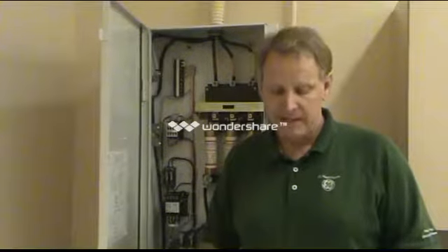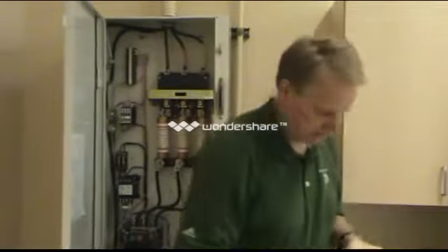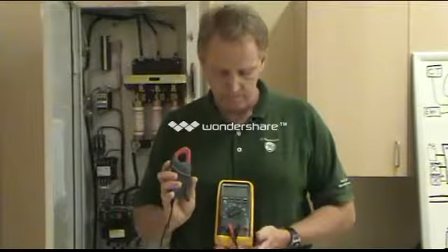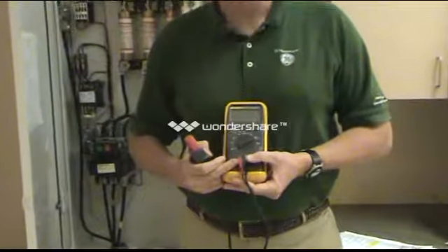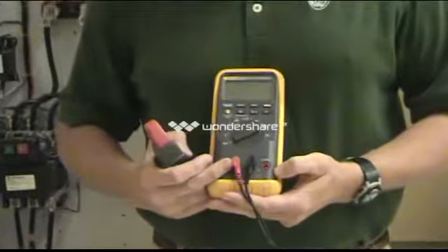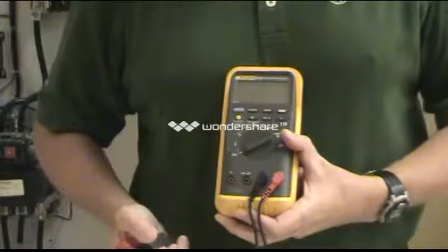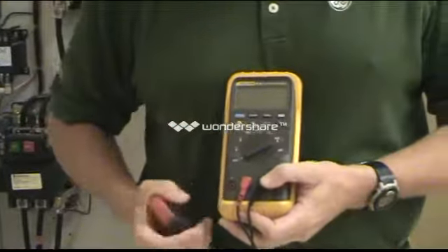Panel currents. This is a section that most people are uncomfortable with. Typically in GE, we haven't been measuring currents, so we're going to go through a proper setup. All right, typical current probe. They go into the milliamp, red goes into milliamp, black goes into common. I've had very experienced engineers put them in the wrong plug out of habit. All right, so milliamp and common.